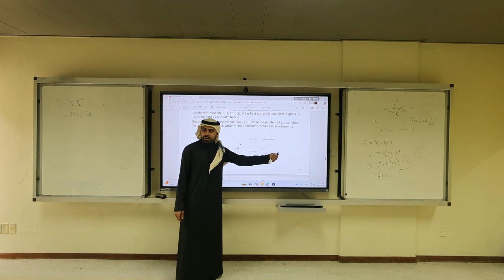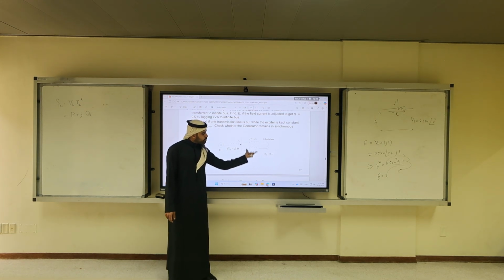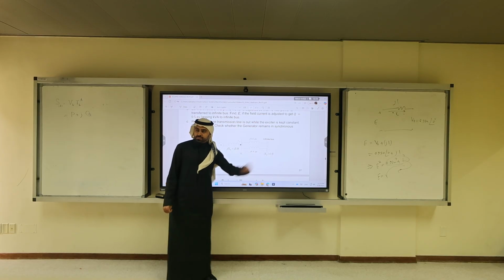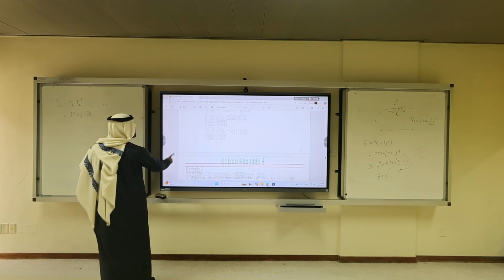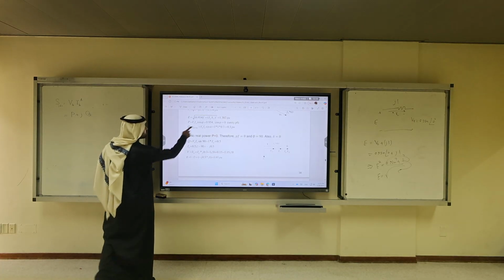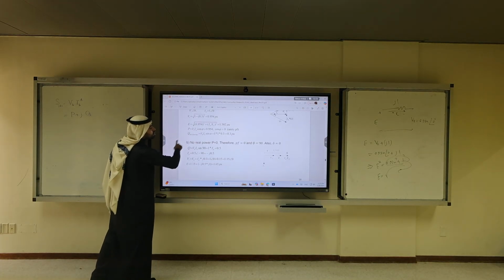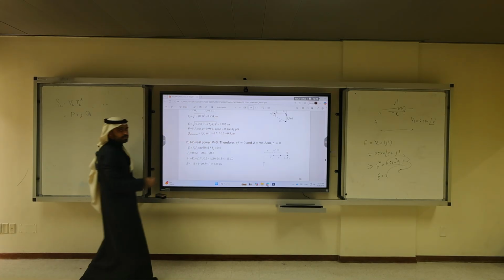But the complex power is not, because we are having those two inductors that would make Q here not equal to Q there. Get it? So to get the real power, he is saying that it is Vt times Ia times cosine theta. Cosine theta is the unity power factor between Vt and Ia.